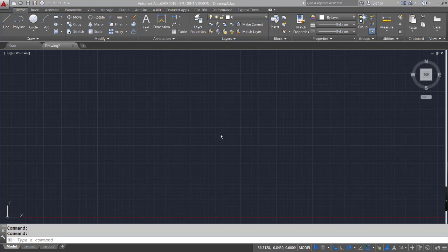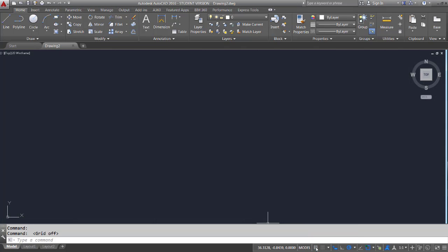And before we start, I think I want to shut off some of the things that AutoCAD has normally turned on for us, because having them off and turning them back on might be a better way to demonstrate this. So you see down here, we have these little icons in the drawing aids area. Anything that's blue is turned on, anything that's gray is turned off. So I'm just going to turn everything off by clicking on it, turning it to gray. And click that, and then oops, that was already off. I turned it on. So now I've got everything off down here, and we see that our screen is just a big black plain area. And that's going to be fine for us because we'll be turning stuff on as we go along.